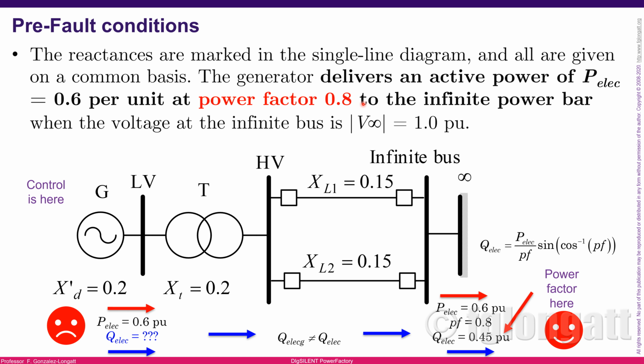This is extremely simple, but this is to show you how important it is to define the pre-fault conditions. And it's your job to understand power system analysis, to know the power system analysis software so that you can properly define the pre-fault, pre-contingency conditions, okay? The first step that I will do is show you the first mistake, okay?